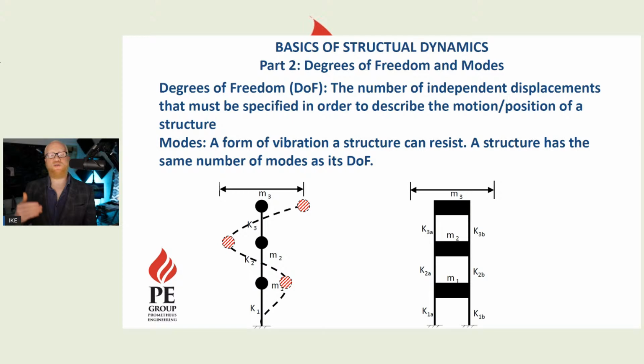So degrees of freedom and modes came into the picture, and we simply expanded the equation because now we just have more masses, more stiffnesses, and more modes, each of which has a natural frequency. So first video, coming up with natural frequency, relating it with stiffness and mass. Now we have more modes, more masses, and so on and so forth, and we just have a series of different vibrations with different natural frequencies which we can relate.